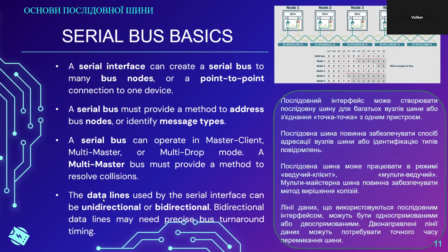And most importantly, because this can happen in buses that are bidirectional and have two dominant states, the power supply for the microcontroller and the drivers must take it into account, which usually means using a switching power supply, which might increase the cost of the device.